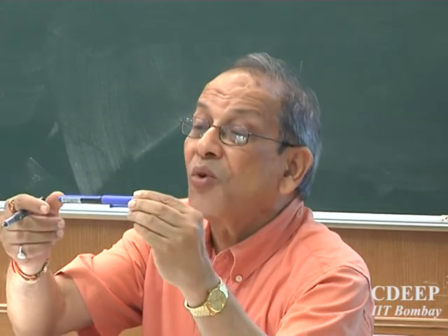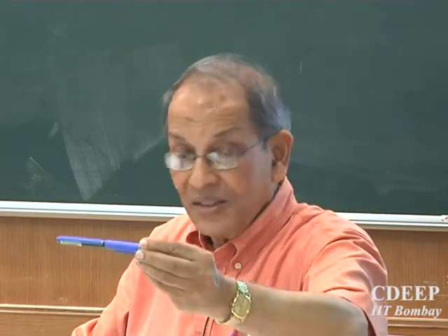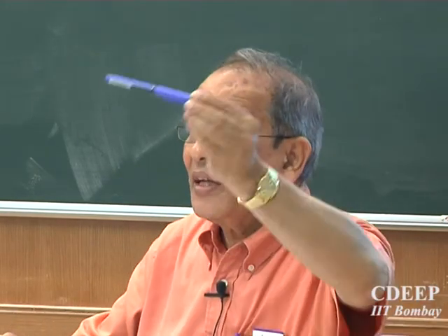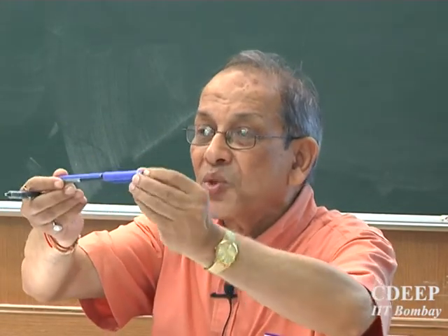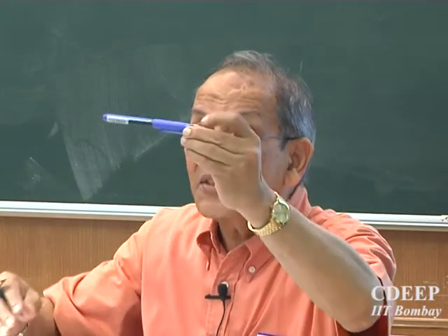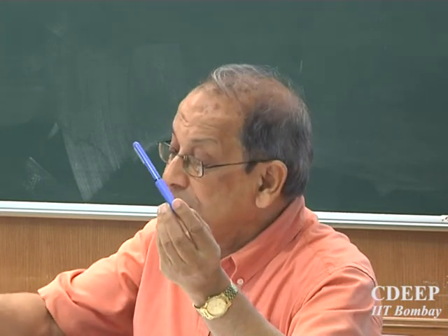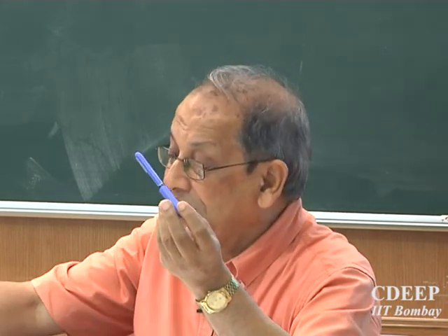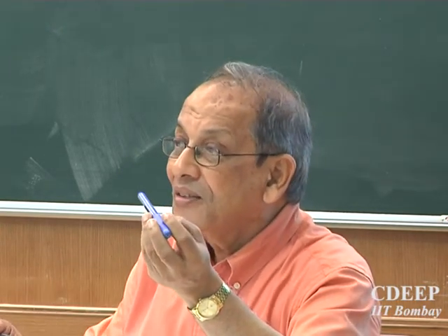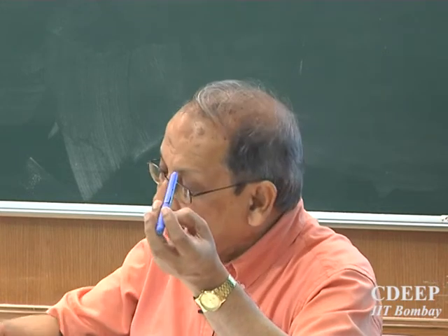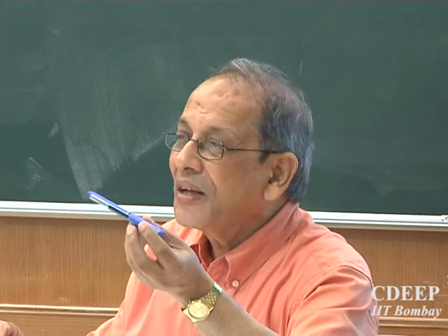Unless I fix this, how can you apply a force? Fix the body in space. Otherwise it will be moving in space. You apply a force, then it will move. It has to be fixed in space, so fix its coordinates. That is called boundary conditions. Just like this body has boundary conditions, but it has been fixed more than necessary. You needed only one end to be fixed, then it was a statically determinate problem. But I have fixed more, extra fixity. Now it has become indeterminate.